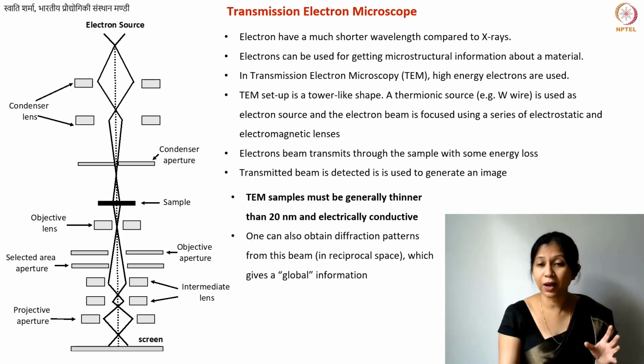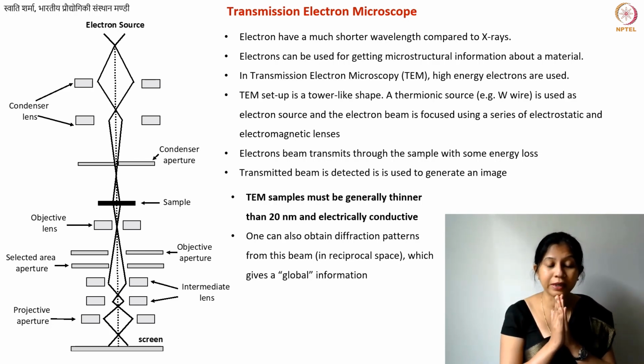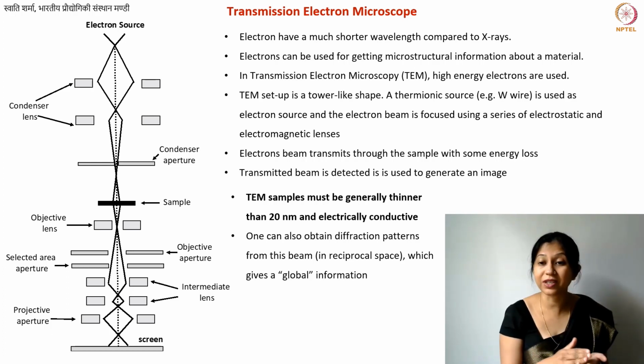That is why it becomes a little bit tricky when you're using, let's say, bulk carbon materials. If I want to take the transmission electron micrograph of a glass-like carbon material, and I purchase glass-like carbon in bulk, in that case I will need to make either a powder or a slice which is thinner than 20 nanometer. You cannot use just some kind of milling or ball milling to make that kind of sample, because 20 nanometer, believe me, is very, very small.